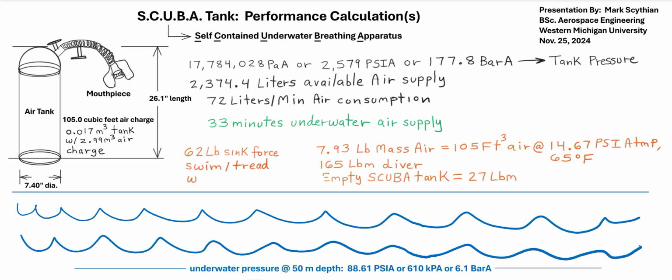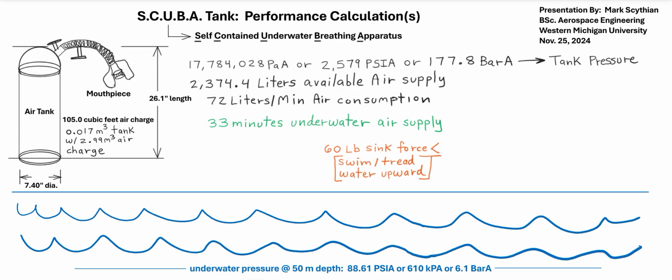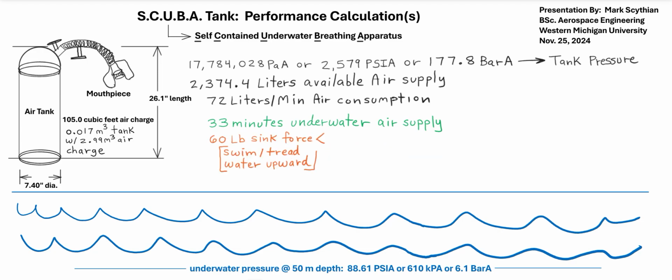However, that is going to oscillate from as low as close to 0 to as high as above 62, but the average buoyancy force is with respect to control authority through the water. So there's about a 10% gradient on that. So it's about 50 pounds of ballast sink force for controllability to sink at a practical rate.